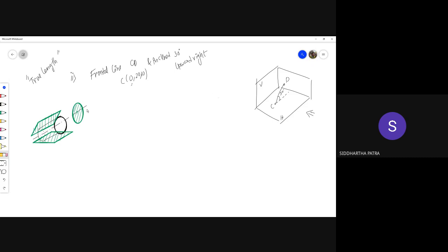Now what is the significance of the true length? When you get true length, you also get its true orientation with a plane, or true angle of the plane. For example, this straight line right here not only makes an angle of 30 degrees with a line that is parallel to the horizontal plane, it makes an angle of 30 degrees with the horizontal plane itself.